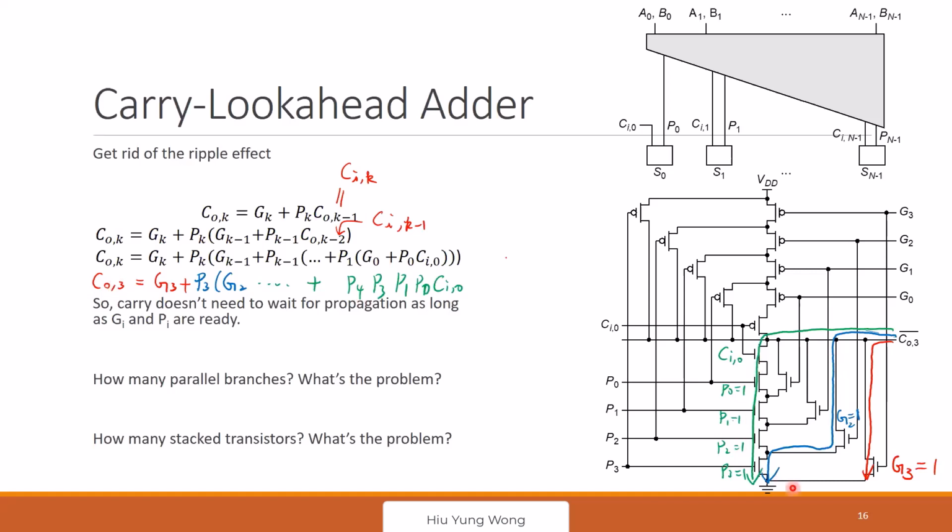So the whole circuit is telling what? Very logical. My output will be 1. Again, this is a negation, so this is pulled down. We add an inverter, and it becomes the real output, right? My output will be 1 if the third bit generates, or the second bit generates and the third bit propagates, or the first bit generates and the second and third bits propagate.